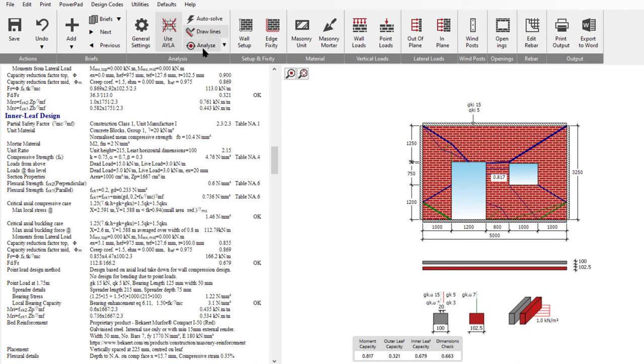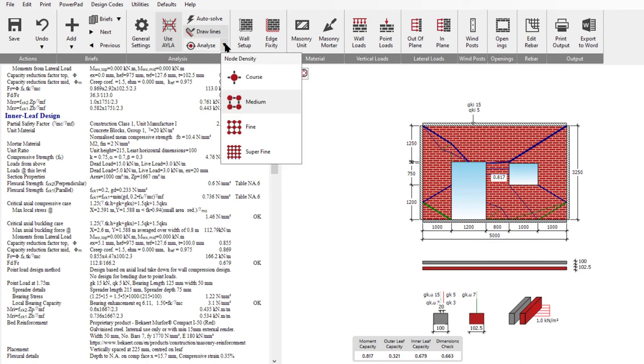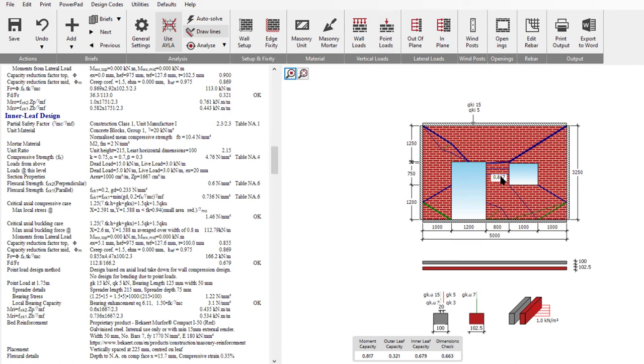And the finer I make my analysis, the more micro yield lines that will occur and appear, because it just is sort of like crack, crack. The same way, you know, slabs will not just crack in one position, they will crack and then another one will come in the secondary to it, provided it's still going plastic. So we can see this yield line.